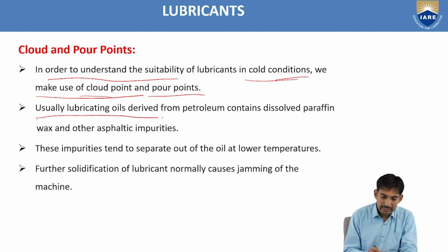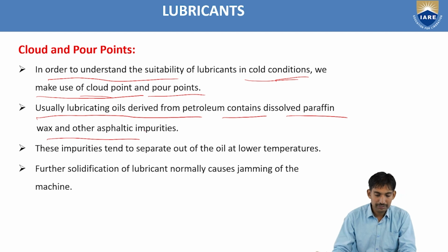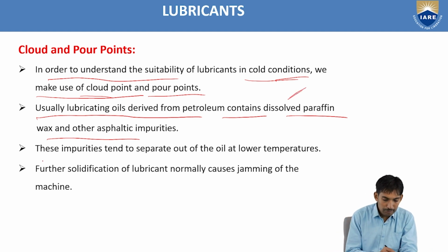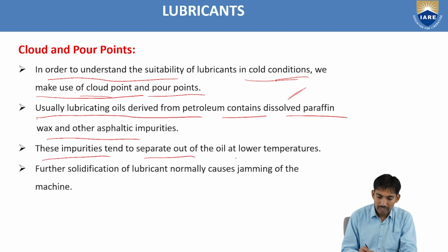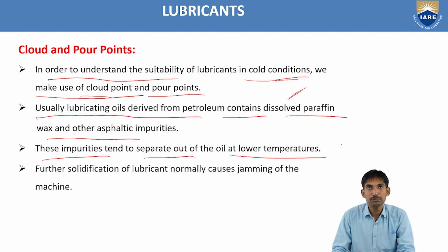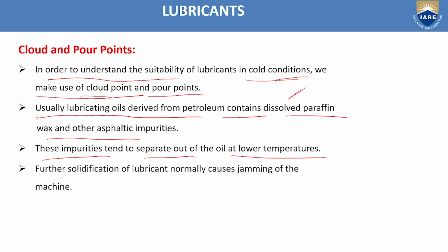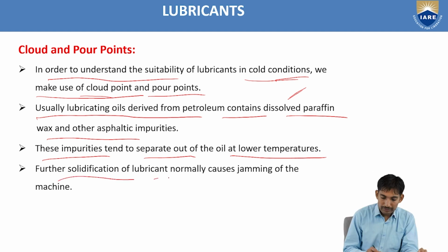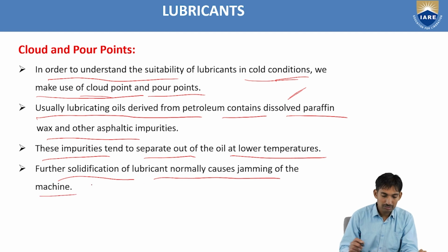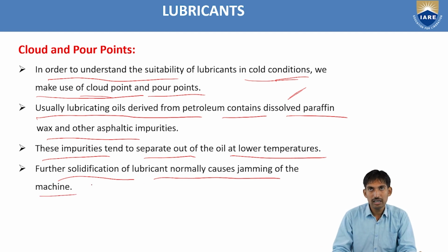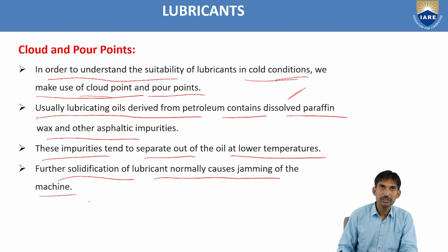Usually lubricating oils derived from petroleum contain dissolved paraffin wax and other asphaltic impurities. These impurities tend to separate out of the oil at lower temperature. Further solidification of the lubricant normally causes jamming of the machine.